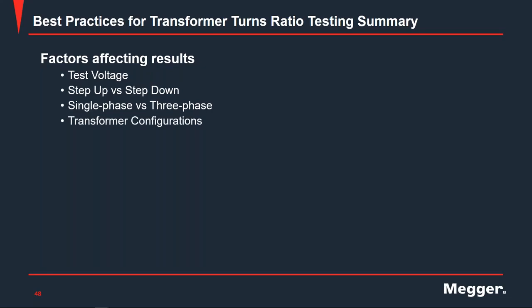And of course, that brings it into the transformer configurations. Again, you could have a DYN1, a DYN7. You want to make sure that you have your leads connected to that transformer properly. You have to make sure you select the correct transformer when you're doing your testing, because again, you do not want to put the wrong transformer into service in a system that is unexpected.